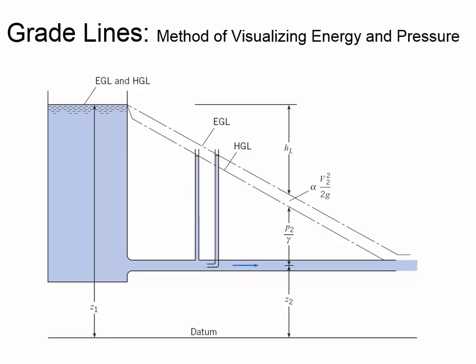And so the velocity head is greater. The amount of energy in the flow is more than just how high the flow is above our datum, the vertical datum. It also has some kinetic energy as well. There's one last thing I want to mention, and that is where the two lines are together inside of the tank, and then they separate.